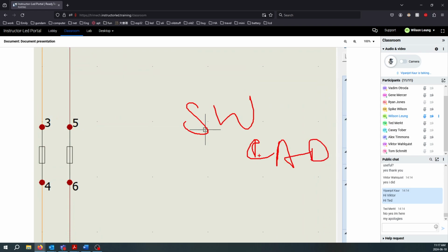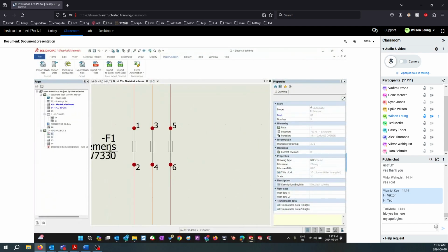So then this guy said, how come the CAD DWG, I cannot import it successfully here and recognize my attributes, my text? The reason is we noticed in the back end in registries that this program, back in the day, they must have bought it from some other company in the older days. So until SolidWorks 2023, in the registries, the SolidWorks Electrical program registry settings are not under the SolidWorks folder. They're under T for Tom. It's called Trace Software.